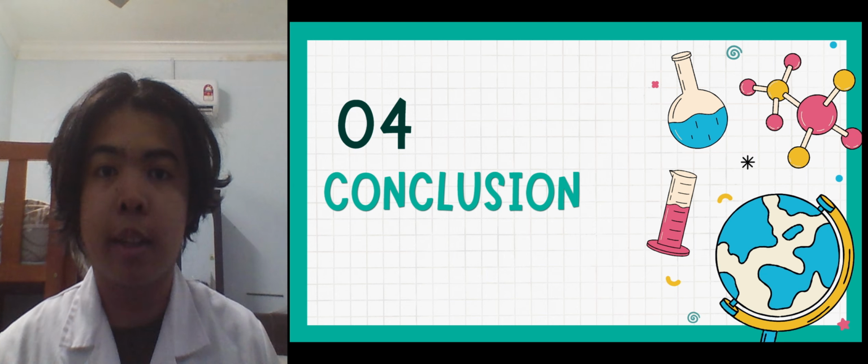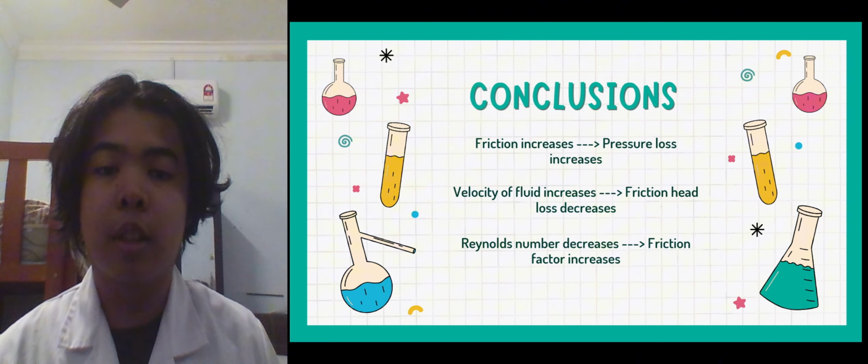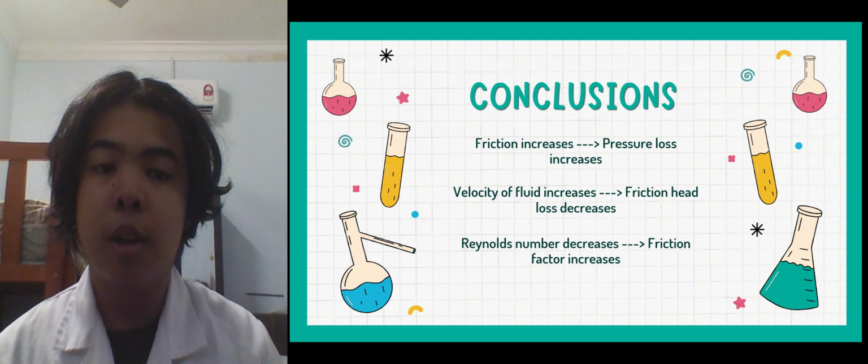Now on to the next part, the conclusion. In conclusion, as friction increases within a pipe, the pressure loss will also increase. This is because friction reduces the velocity of the fluid flowing through the pipe, which according to Bernoulli's principle leads to a decrease in pressure.